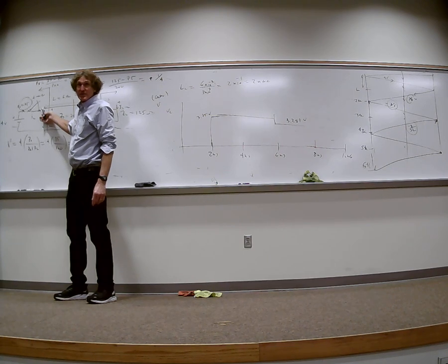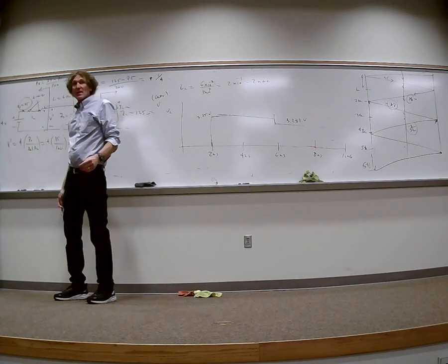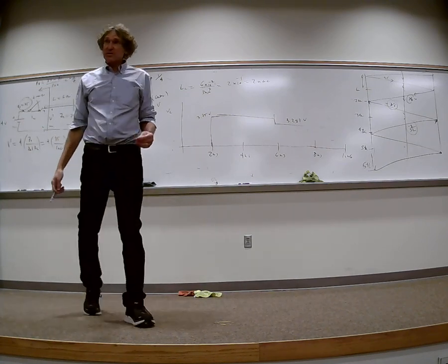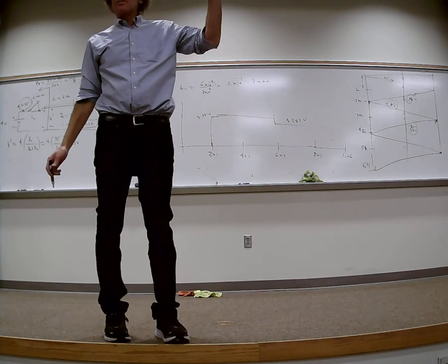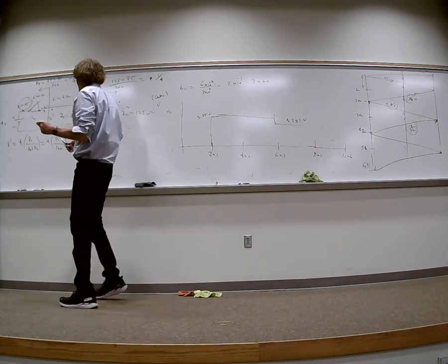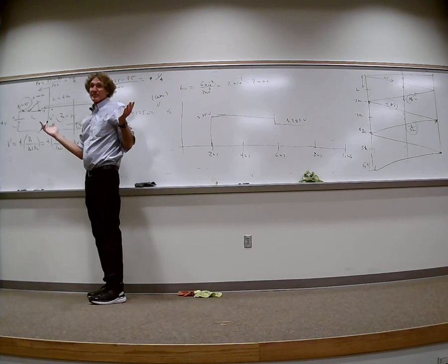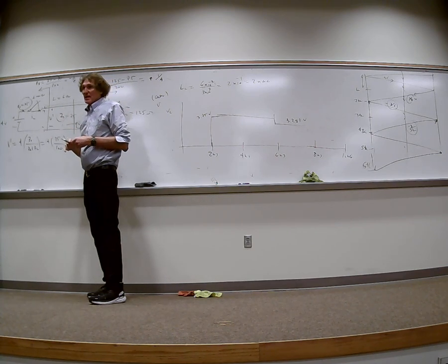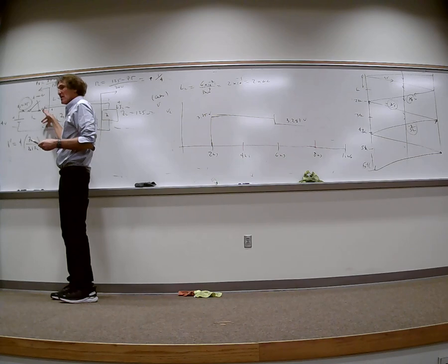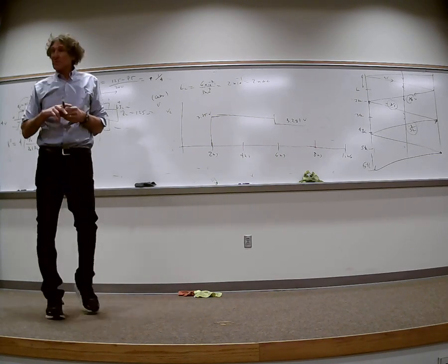So you find the voltage here, subtract it from 4, that's the voltage difference across the resistance divided by the resistance. How many understand that? It's important you don't mess that up, because I say this all the time. Even students that are graduates, they'll take this voltage here and just divide it by Z0. They get careless, that's wrong. It's the voltage here minus the voltage here divided by RS, so you can figure out the actual voltage difference.